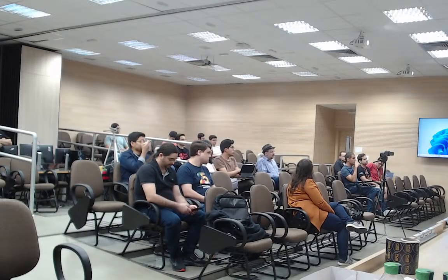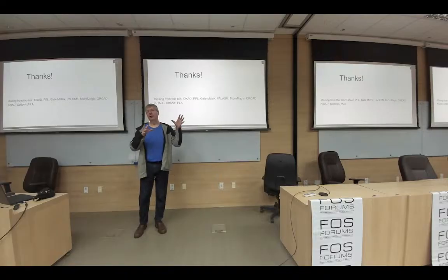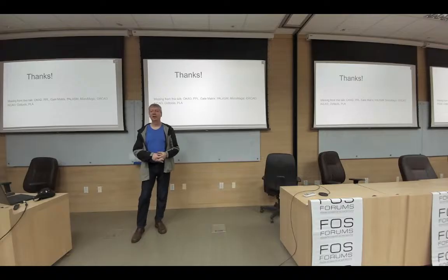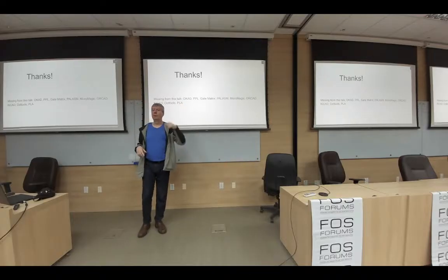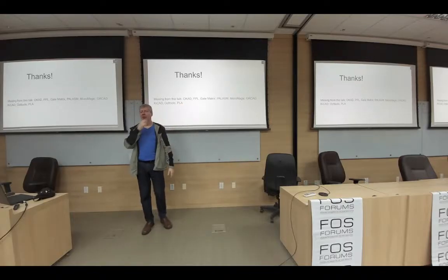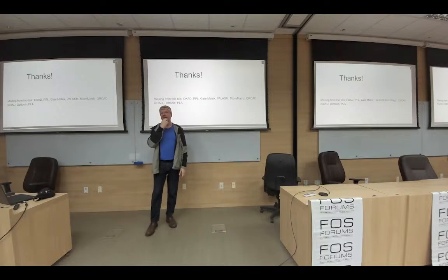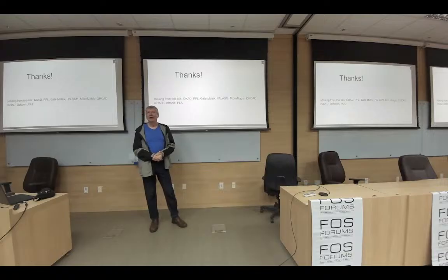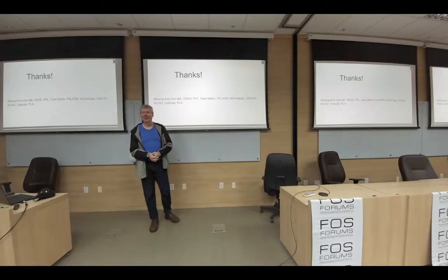Yeah. OpenROAD was a bunch of scripts in a language called TCL, Tool Command Language, that started out in Magic. These called a bunch of Python scripts that then called a bunch of C++ programs. Some of the boxes that weren't labeled were the ones that do the placement, the routing, or whatever. And so these are a bunch of student projects thrown together, and it works, but it's not as clean as something that you paid $500,000 for. You get the advantage. I don't see it as $500,000 worth of an advantage, but you do get an advantage out of the commercial tool.